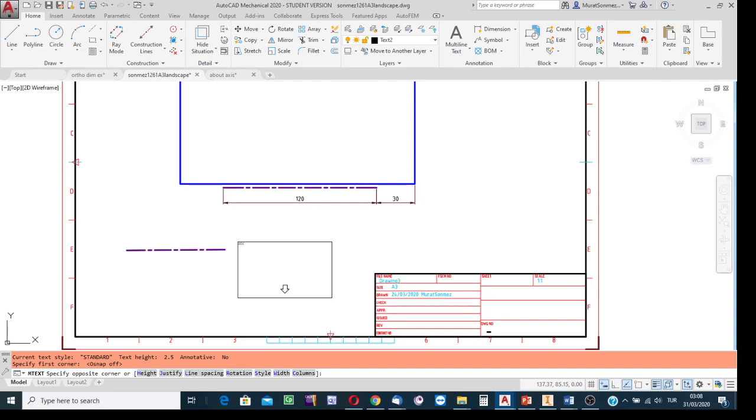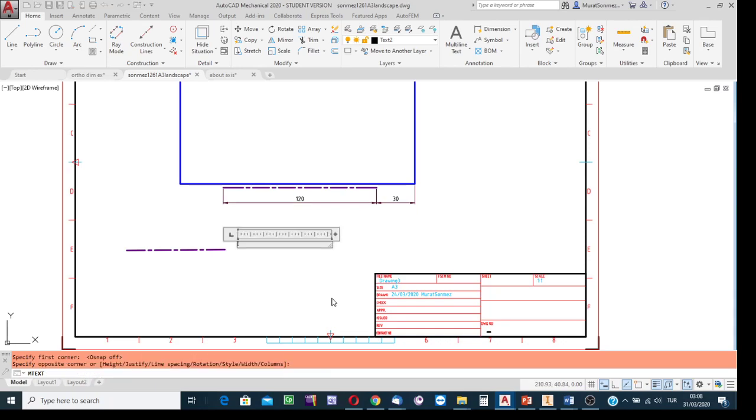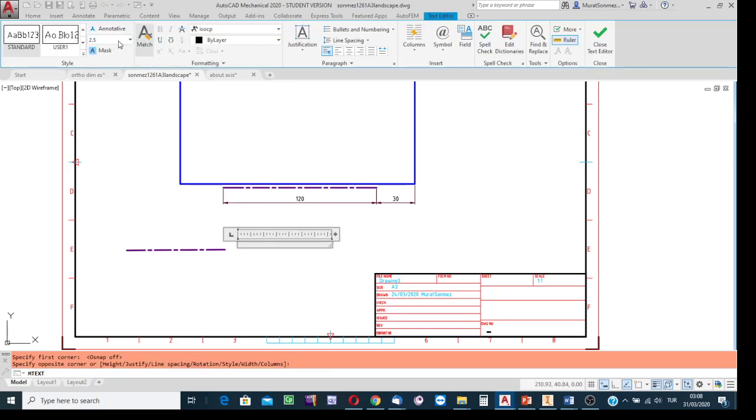After making the second click, find at the top along the ribbon a new ribbon, the text editor ribbon. In this dialog, select from the list, if it exists, the recommended font height. If the font height is not in the list, then you can type it. Into this box, write 5 for instance, press enter.